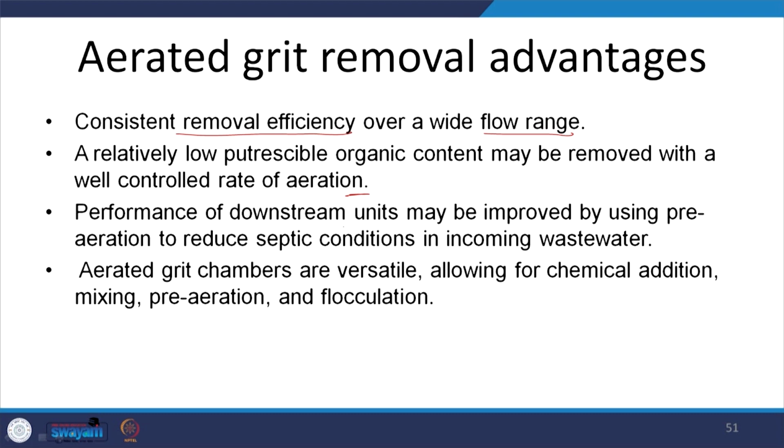Performance of downstream units is improved, or can be improved, by reducing septic conditions in incoming wastewater. Why is that? Because here we are pumping in air that contains oxygen. So, that is one aspect. Aerated grit chambers are versatile, allowing for chemical addition or mixing, pre-aeration, which is the key, and sometimes it allows for flocculation. That is one aspect to keep in mind.